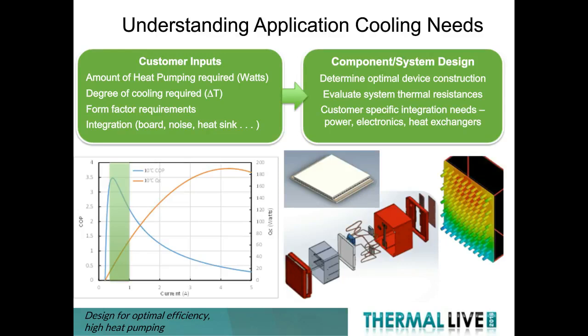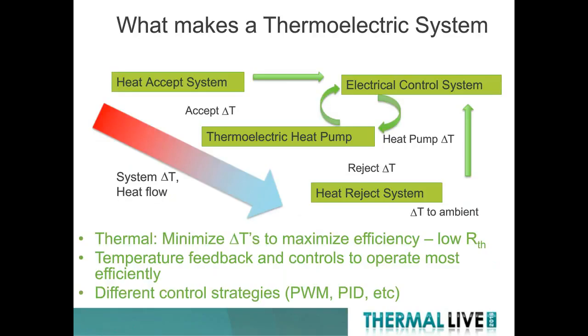Mm-hmm. So, just expand on that a little bit in terms of what are the subsystems that designers should think about when they're designing with thermoelectric devices? Probably the most overlooked is the thermal interface. So that is the actual contact between what your heat exchange mechanism is and the actual device itself, with relation to how those devices move heat from one place to the other and what's required to do that.